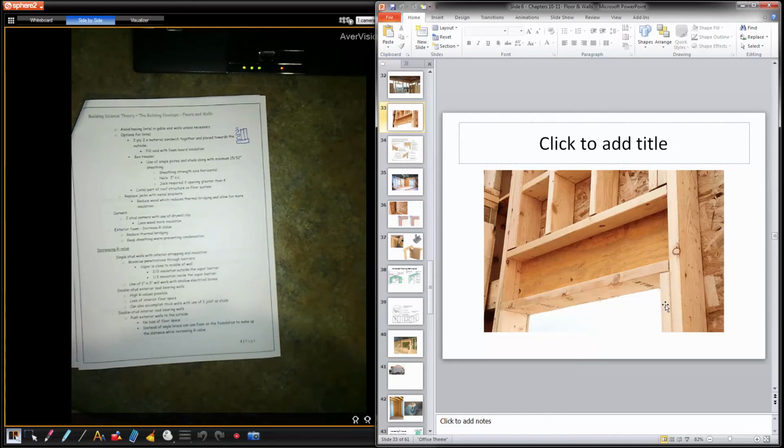So the jack should go all the way up and hit the lintel. Again, this plate here shouldn't be there, or it should stop here. That side's correct. Oh no, that side's not correct, because there's another window most likely overhead. So that jack should come through and sit on top of the lintel. This jack should come through and hit the lintel. This jack should hit the lintel. That jack should hit the lintel. I have a feeling there's another window overhead there.